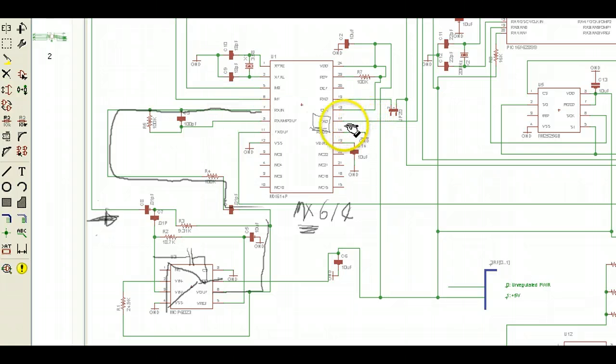So in review, audio comes in here and DC comes out over here, ones and zeros. The 1200 Hz tone may be represented as a 0, whereas the 2200 Hz tone may be represented as a 1. And of course, these are some control signals. This is an oscillator that drives this thing, and these are control signals, and you can look them up on the web. Actually, this is a duplex chip because it takes data in and puts out tones, but we're working on the receive portion today.